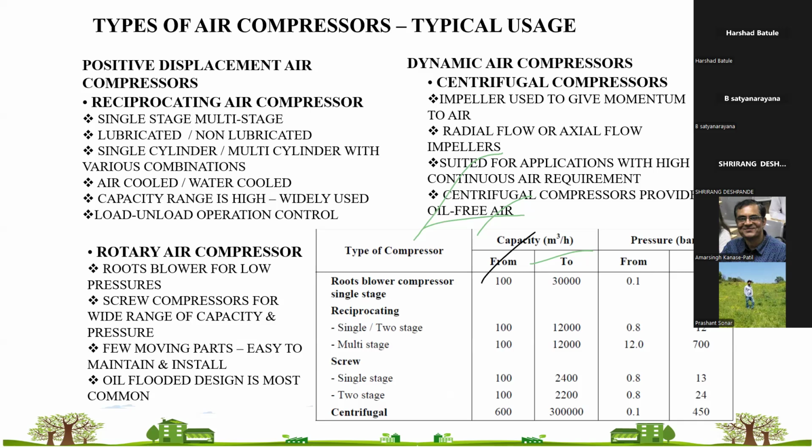Like in kcal per hour, heat rejection will be in kcal per hour. That kcal per hour will be converted to TR for HVAC, but kcal per hour will be directly used for a boiler, or kcal per hour will be converted into tons of boiling or heating. Then kcal per hour is used in a thermic fluid heater as such. So those units can be applied differently to different utilities.